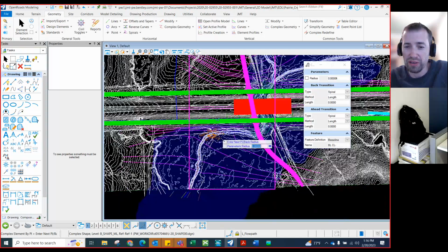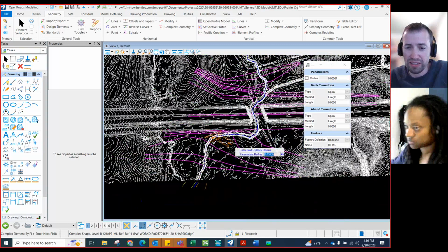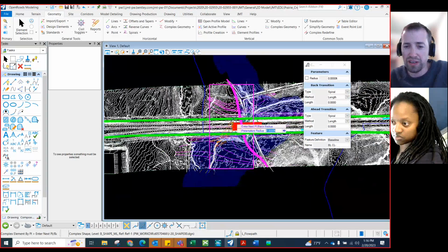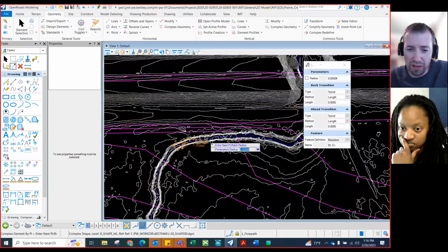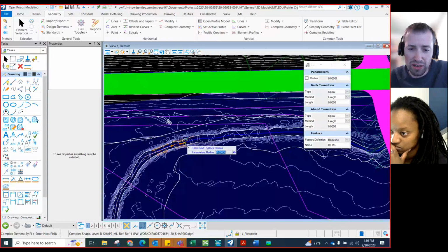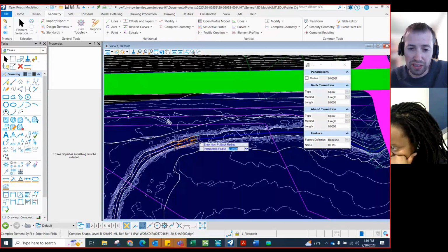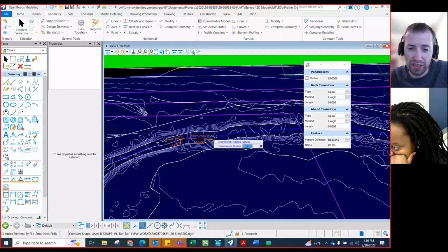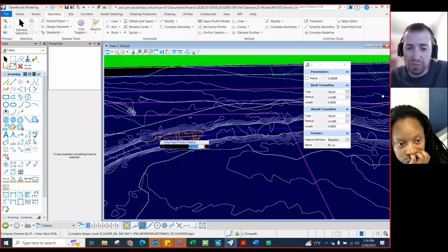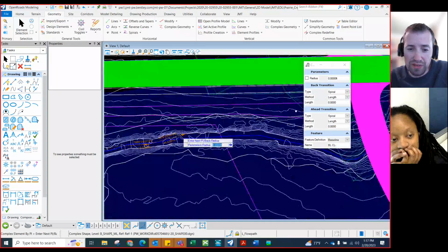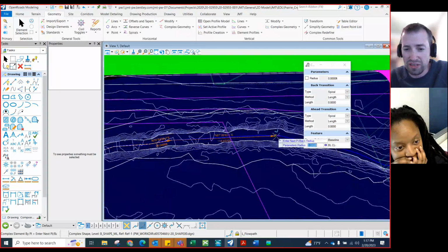We need to look more carefully at what's immediately surrounding, and we can care less about the stuff that's way downstream of us and way upstream of us. We're going to try to make our modeling tie into those water surface elevations upstream without any increases anyway. So this model was made specifically for this crossing, so it's about the same extents as I'm wanting to look at.